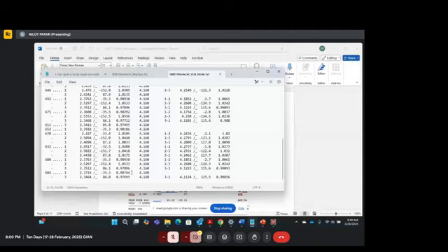This is a kind of validation that you have to do every time you do any kind of modeling in distribution software. It can be OpenDSS, it can be GridLab-D, or any other modeling software. Suppose you are in the utility, you have certain meters and meter data over the previous year, and you model the whole system in OpenDSS and you run power flow.